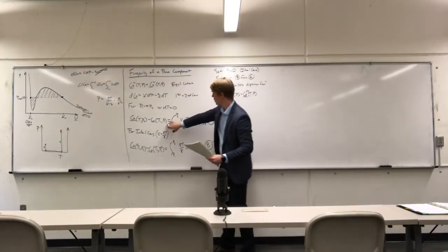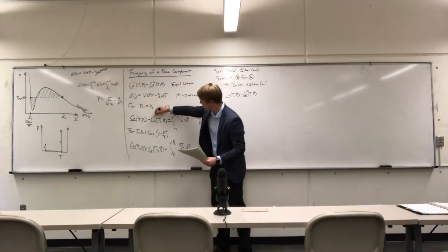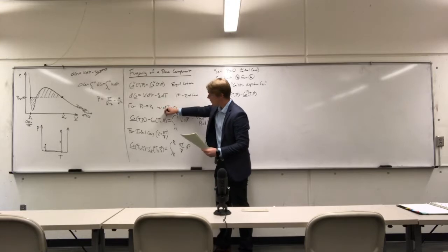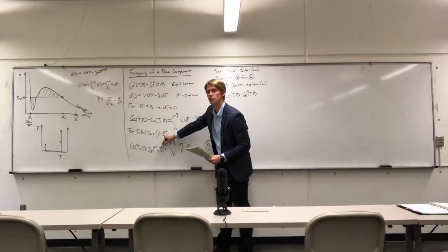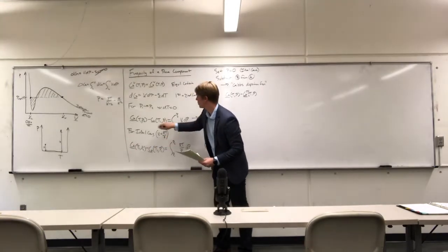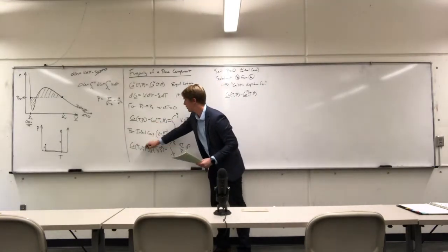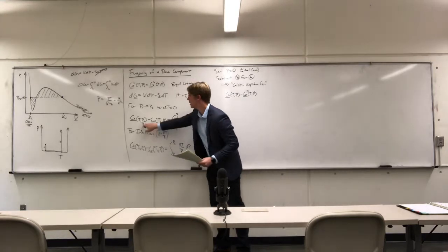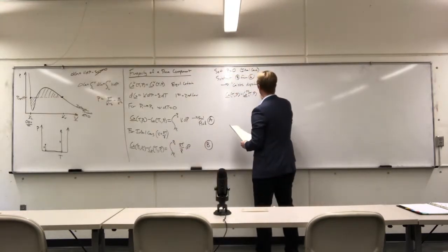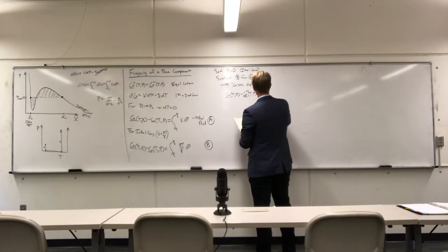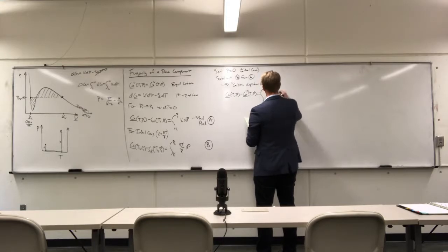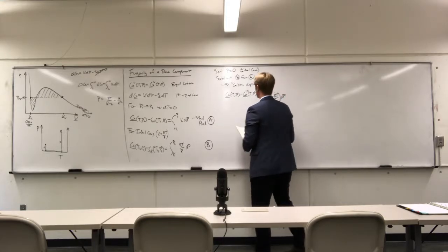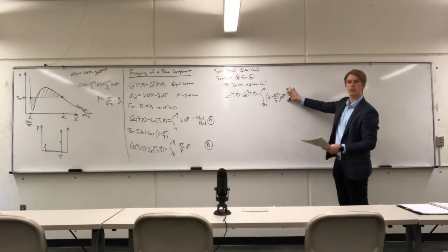Right, because in this equation here, expression A and B, this term, this is the ideal gas state because it's at pressure 1, which is 0. This one's at pressure 1, which is pressure 0. So these terms cancel each other out. So we're just left with these two lingering ones, the ideal gas and the real fluid. Okay, this is the Gibbs departure function.